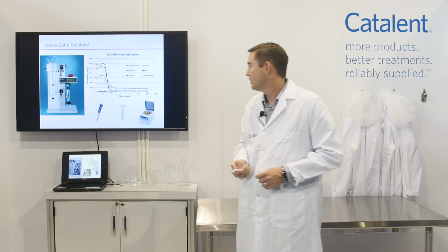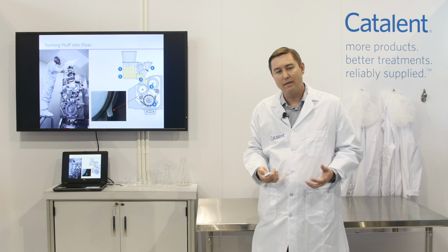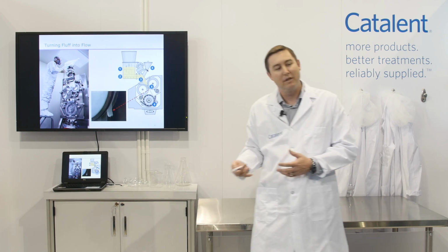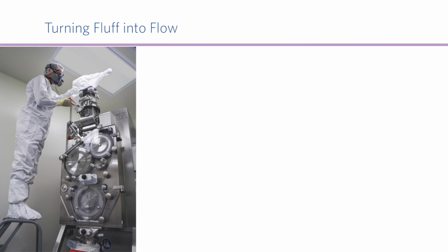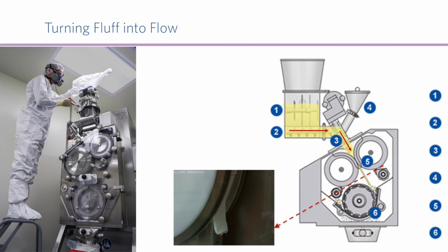As I said earlier, the material that comes out of a spray dryer is beautiful in the sense that it's going to give you better solubility, but from a downstream processing standpoint, it's a little bit bulky and doesn't flow very well, so you need to have roller compaction typically used to process that material into something that can then be put into a capsule or a tablet.